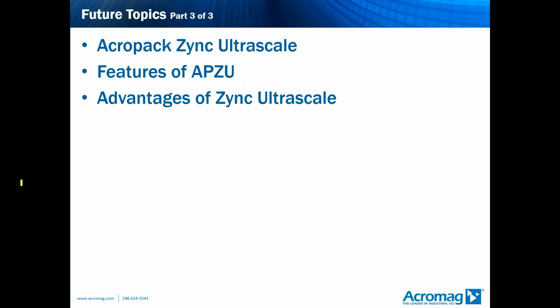Yes, for older versions or for older boards that we have, like the Spartan, I believe that's a Spartan 6 board, the PMC SLX, XMC SLX, you're not going to be using Vivado for design modification. You'd be using Xilinx ISE. So it's a bit different. It's a different method of how to do that. But our more modern stuff like the 7 series, absolutely very similar to what we did here today.